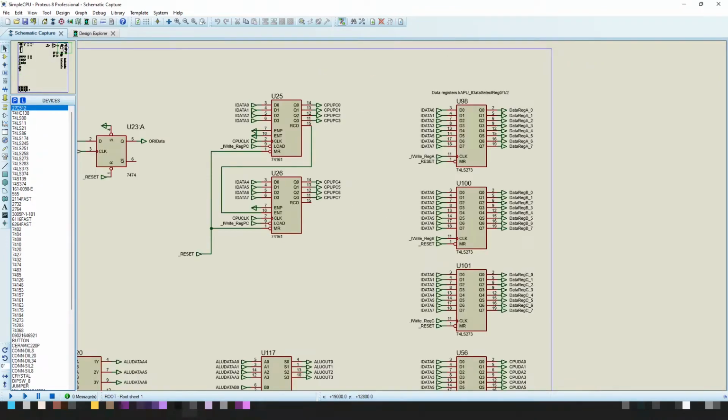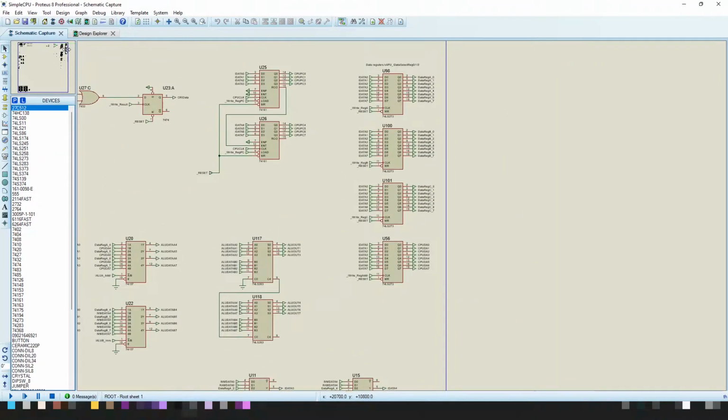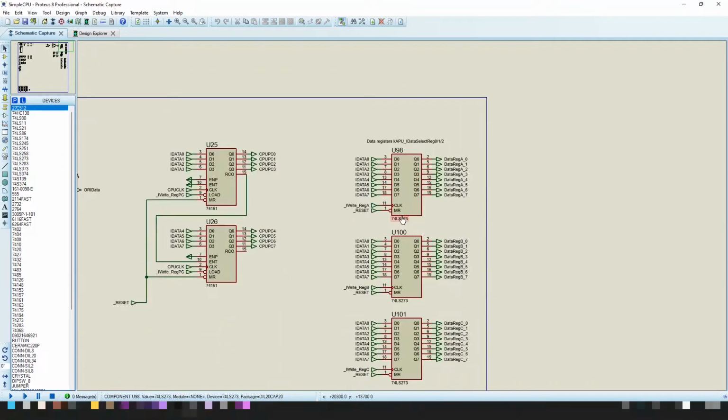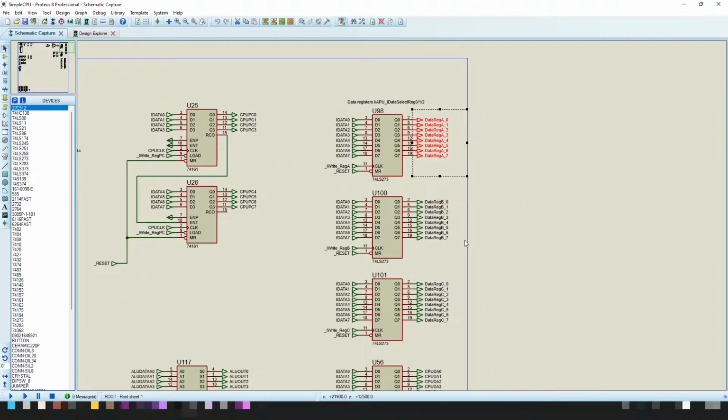The next part of the design is up here in the top right-hand corner of the design. So these 4 latches here represent from top to bottom the address registers A, B, and C, and down at the bottom we have the address register. They all use the same latches. They optionally latch the data that's held on the input data bus, and then they present it on their relevant outputs. All of these outputs are discrete signals. They don't conflict with each other. They're on separate buses, because we select them later on, and I'll show you these selectors in a minute.